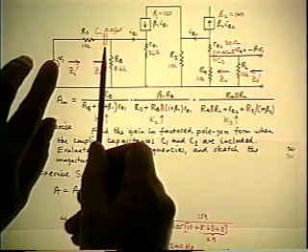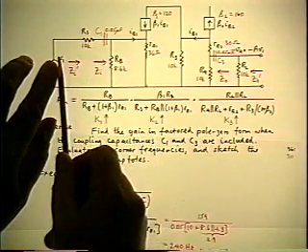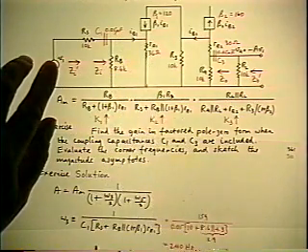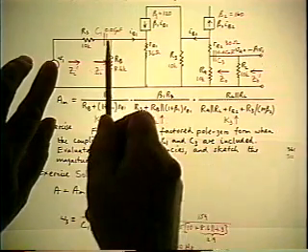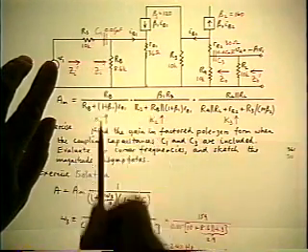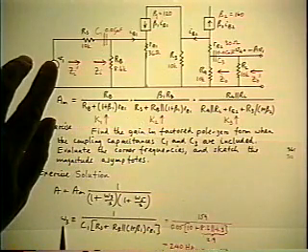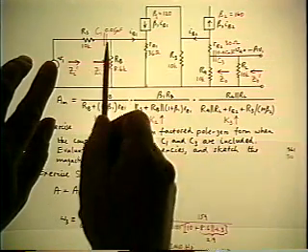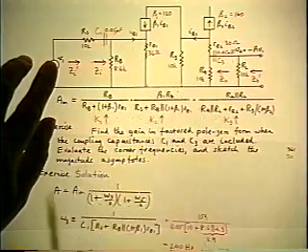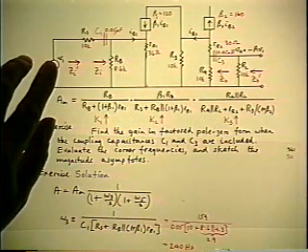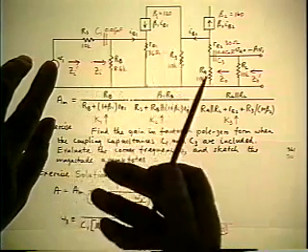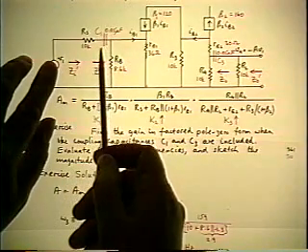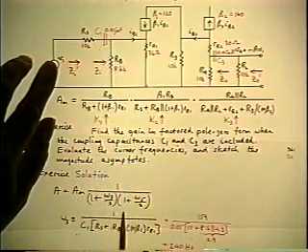So looking in place of the C1, you're going to see RS to ground in this direction, RB parallel the reflected RE1 to ground in the other direction. So that's the value of RD, which together with the C1 eventually is going to develop the pole. So that's the omega 3. And it's an inverted pole because the reference gain is infinite frequency. Now, in fact, this is, of course, the identical problem we did earlier as an example, where we put this capacitor in. So that's the same result.